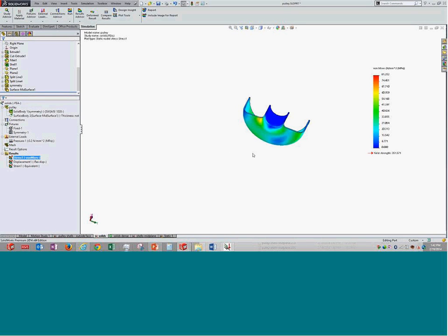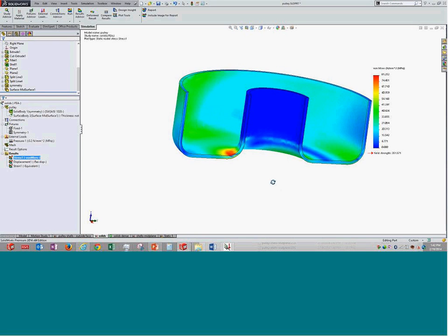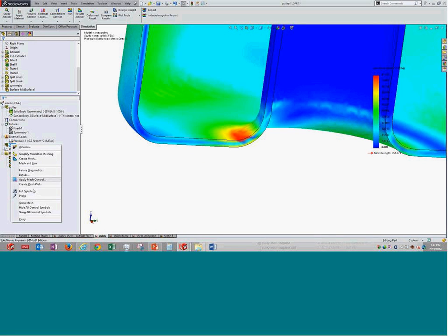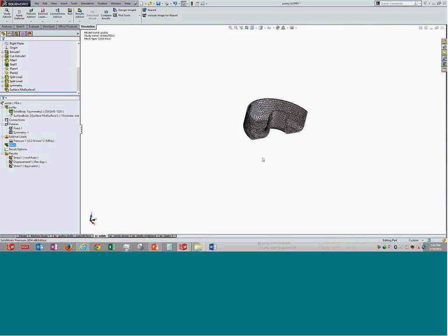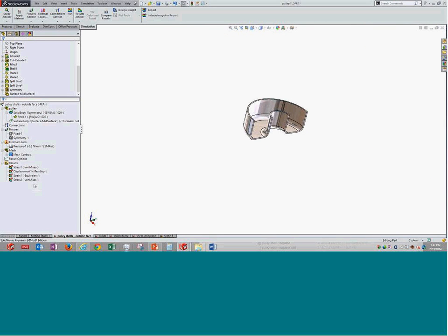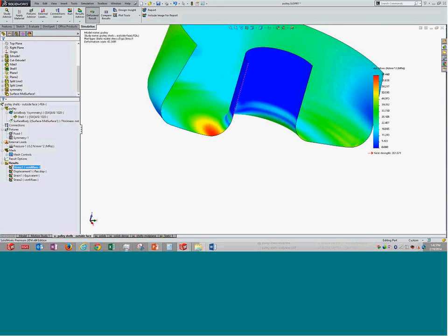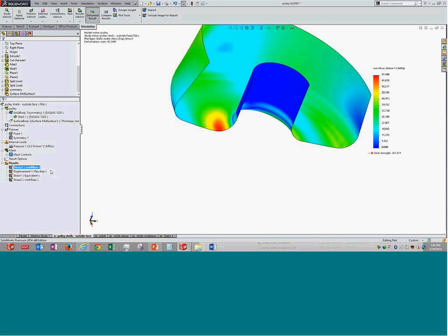It is only 1 meter across the thickness, and finally this one is 10 megapascal. So there is scope for refinement over here. By the way, for shells, we also have the option of looking at results at the top plane and bottom plane. We can find membrane and bending stresses. So that is available here.